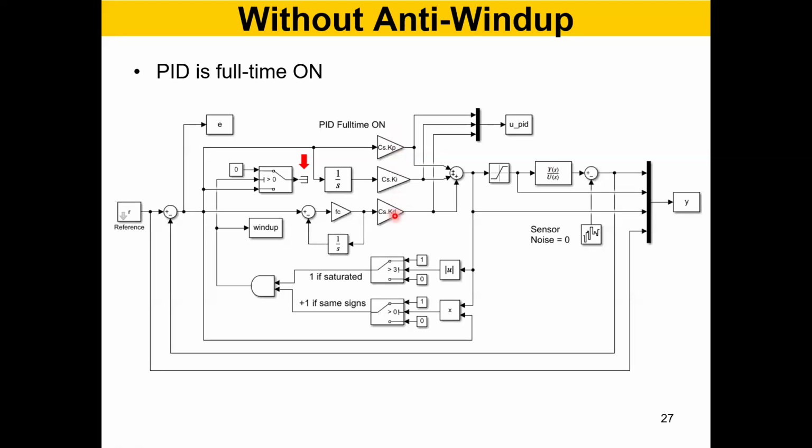All right. In MATLAB, it's just a single command. If you know the transfer function, right, you can generate the reasonably acceptable PID gains. And then we use these gains here in the Simulink. Now we have MATLAB M file and Simulink block working together.